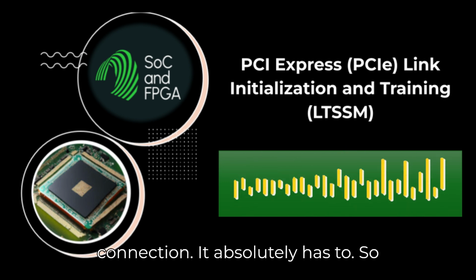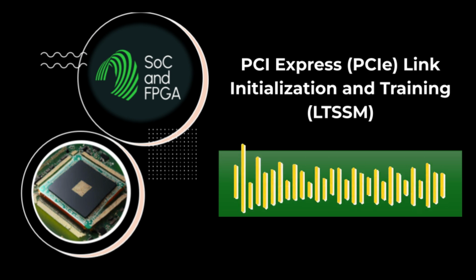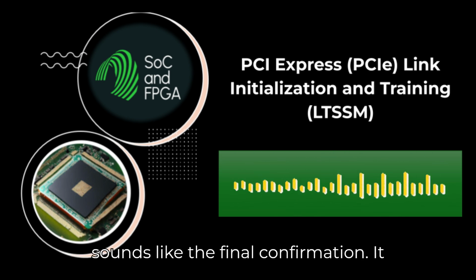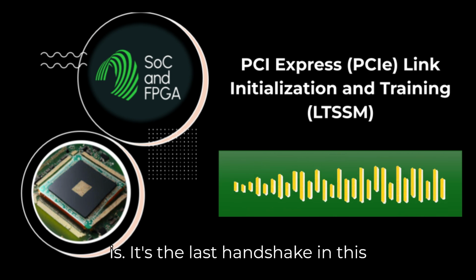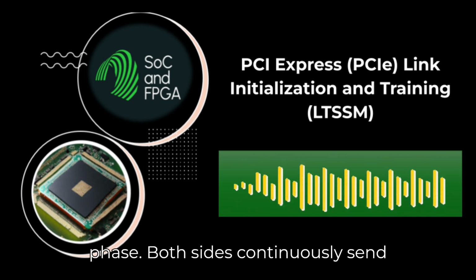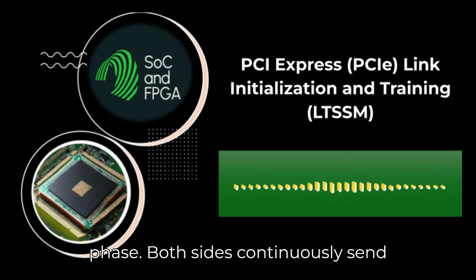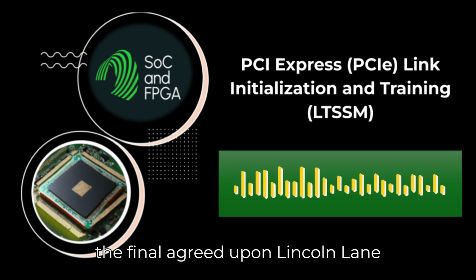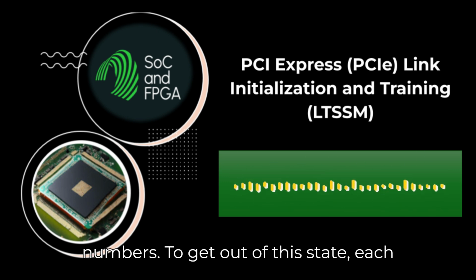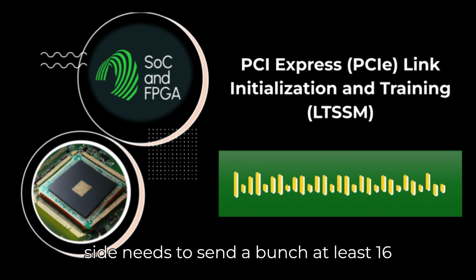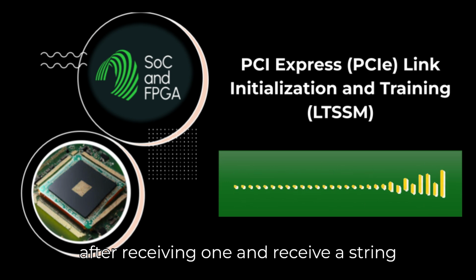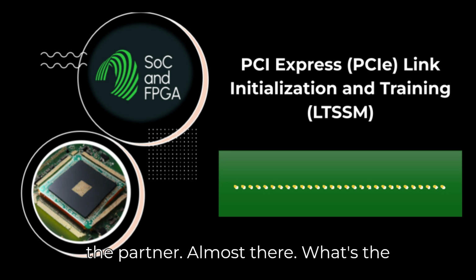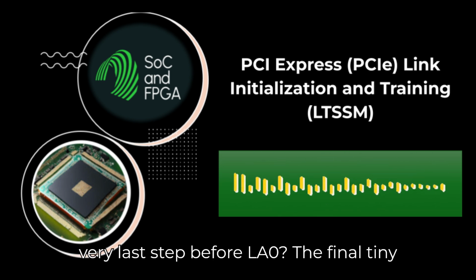It absolutely has to. So assuming they finally agree in Lanenum.Accept, they move to Configuration.Complete. What happens there? Complete sounds like the final confirmation. It is. It's the last handshake in this phase. Both sides continuously send TS2 ordered sets now. These TS2s contain the final agreed-upon link and lane numbers. To get out of this state, each side needs to send a bunch, at least 16 after receiving one, and receive a string, like 8 consecutive, of matching TS2s from the partner. Almost there. What's the very last step before L0?